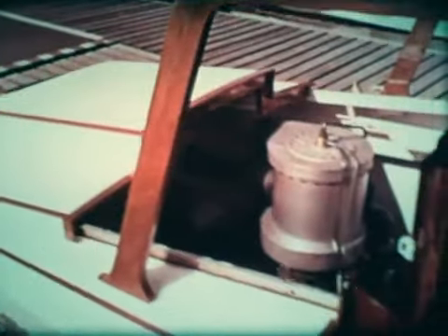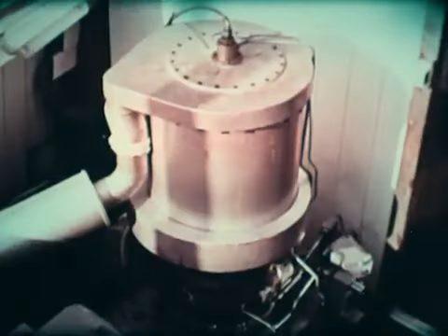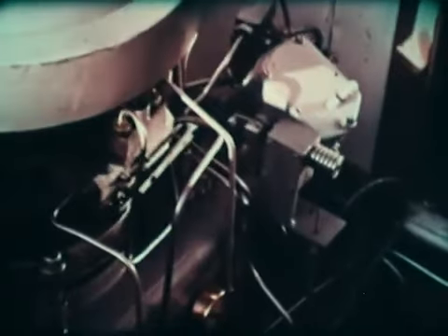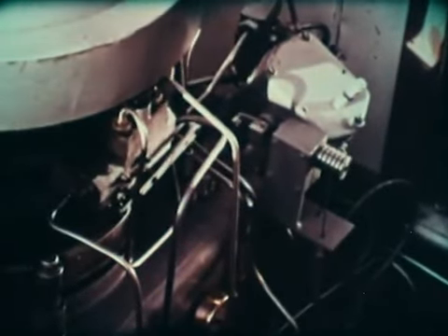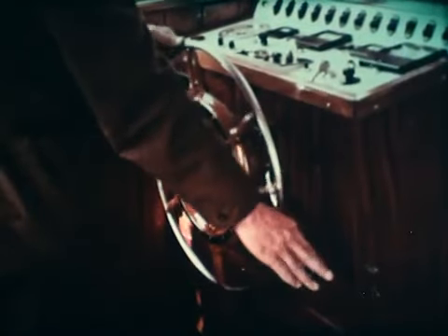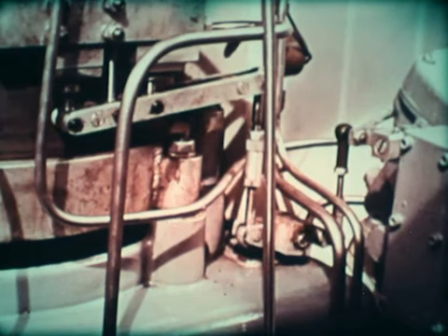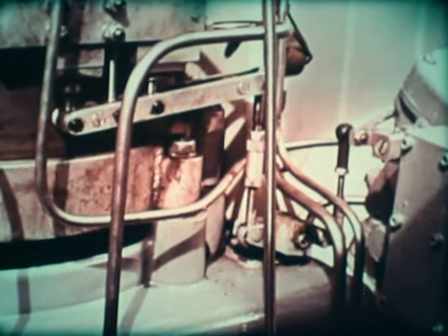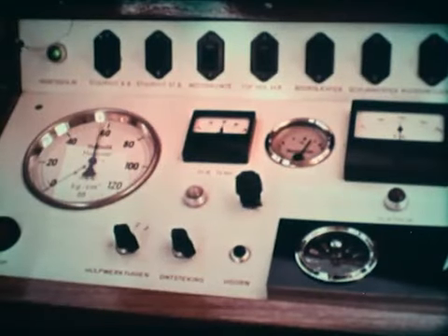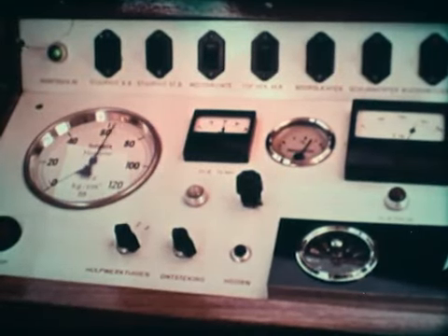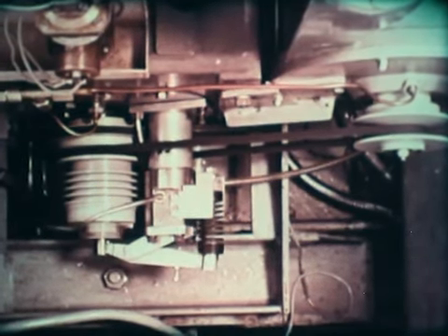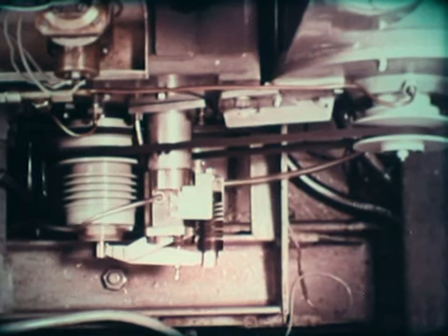The large cylinder is the preheater fitted around the head of the engine. The fuel atomizer is seen at the top. The power output of the engine is proportional to the mean working pressure. If the governor is set to a higher speed, helium from a high pressure bottle is blown into the cylinder, quickly increasing the working pressure and the power. The pressure also controls this variomatic drive of the blower that supplies the air required by the burner and keeps the air-fuel ratio constant.